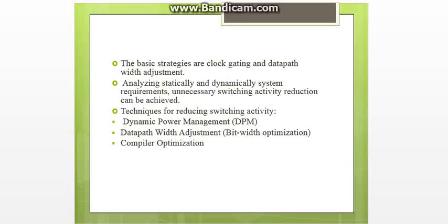Bit width analysis is performed to extract information on the required bit width of variables in programs and algorithms. For hardware design, using the result of bit width analysis, one can determine the length of registers, the size of operation units, and the width of memory words on the data path of a system to minimize the meaningless power consumption by the useless bits. Shorter registers and operation units reduce switching activity and the leakage of extra bits on the data path.